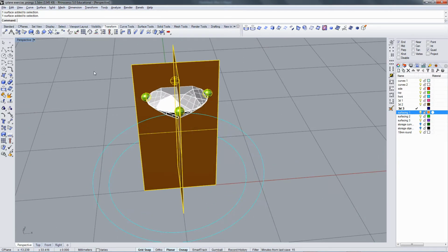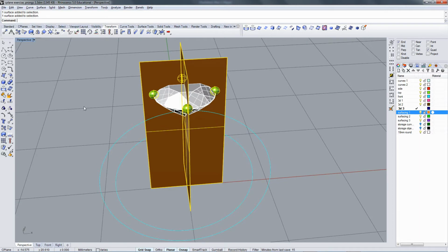For an emerald cut, or a marquise, or a pear shape, or an oval, any of those, the angle of the prong has to be specific to the stone. It's not very successful generally to try and model the prong using a standard C-plane configuration, and then try to orient that prong to get it where you want it. It's possible, but you're going to make decisions that perhaps would not be valid. So I would always recommend to model those prongs in situ at the angle that they need to be.